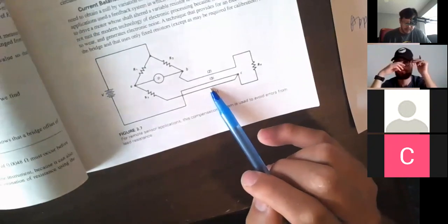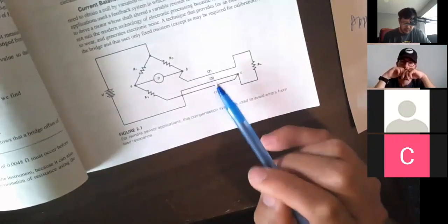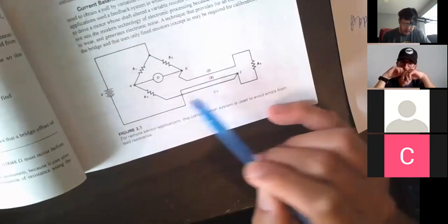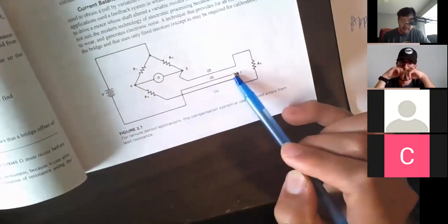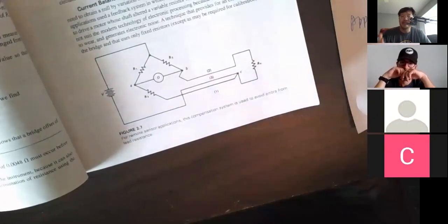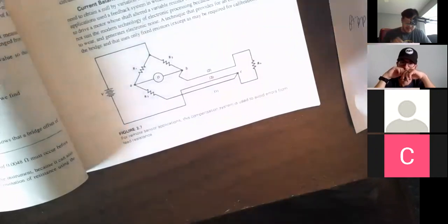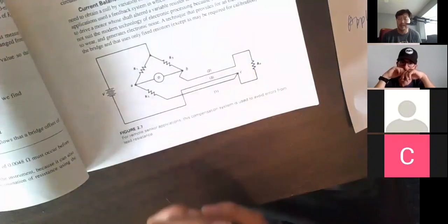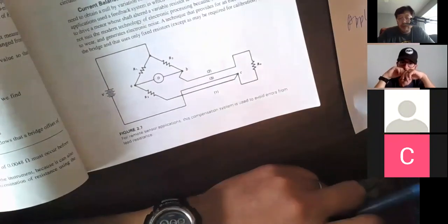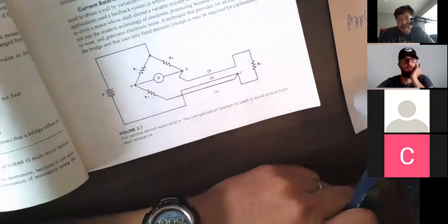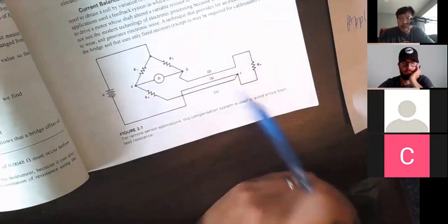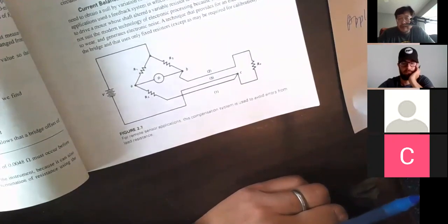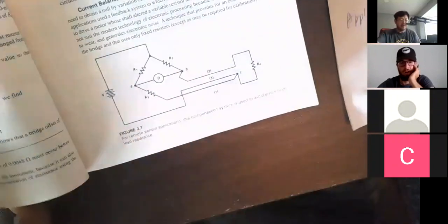Same thing for wire number one. Why does wire number one cancel? Okay, I'm sorry. Wire number one and wire number two are on both sides of the bridge, so they cancel. How about wire number three? The resistance doesn't matter either, because that only changes the power, like reducing the battery power a little bit. So it doesn't affect the reading of your temperature. So the resistance of all three wires doesn't matter. So this is very good. Cancellation.